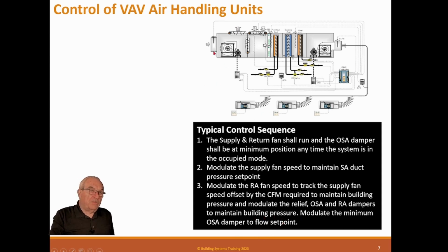I don't know if you remember when we talked about economizers in the constant volume training video, that we talked about trying to balance this condition between economizer and normal operation, because this was a constant speed fan that requires some talent to get that balance. These are not constants, so we can actually fool with these dampers, which makes it easier.